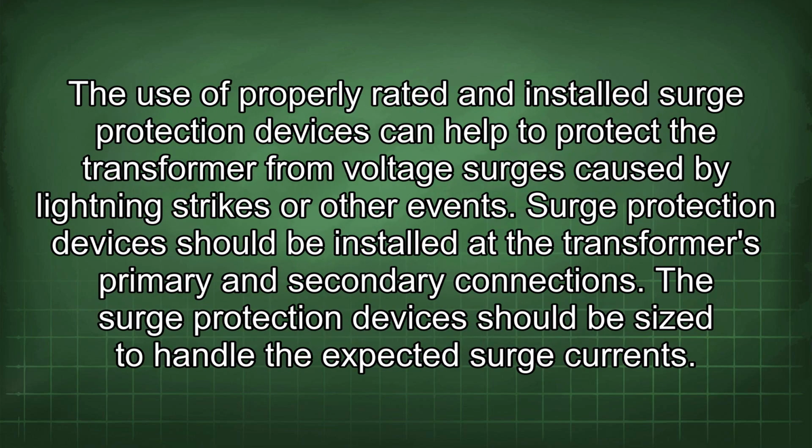The use of properly rated and installed surge protection devices can help to protect the transformer from voltage surges caused by lightning strikes or other events. Surge protection devices should be installed at the transformer's primary and secondary connections. The surge protection devices should be sized to handle the expected surge current.